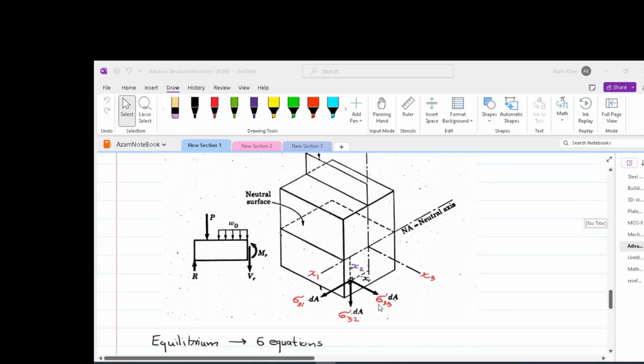So we have one stress which is out of plane and two stresses which are in plane. Since this cube has six faces, at every face we will have three stresses, which gives us 18 stresses altogether. Later we will see that these 18 can be brought down to 9 distinct stress components.